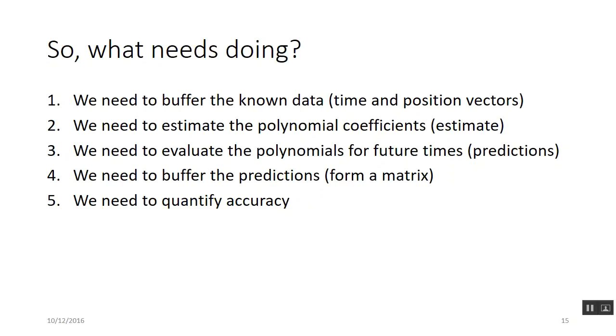Then we need to take those two buffers and every time step shove the whole buffer into a polynomial fit algorithm, which actually Simulink doesn't have the kind we need. So we're going to hack an algorithm and look underneath the mask of a Simulink block and create it the way we need it. Because they have, I'll show you, we just have to work around what it does.